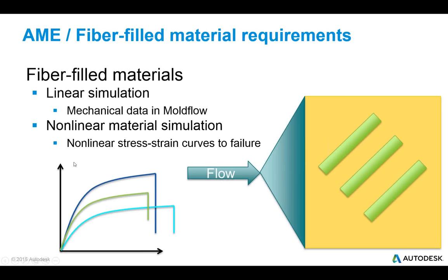The cool thing about the 2016 release of both MoldFlow and Advanced Material Exchange is that now you can also enter these curves in MoldFlow, and that data will be transferred automatically into AME when we read in the study file. So that's really powerful. Now you can have a single source of the data that's run with both the MoldFlow and the structural simulation.